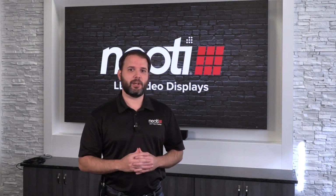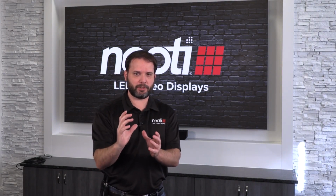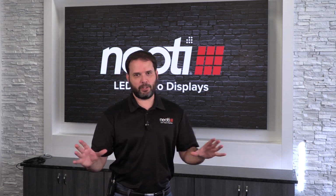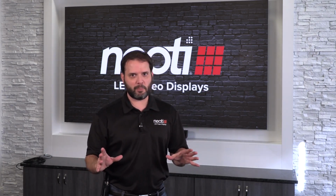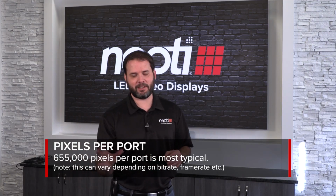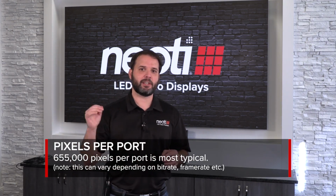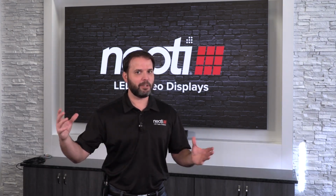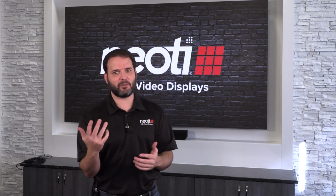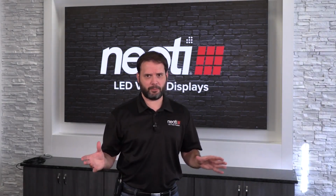Current DirectView LED systems have a load capacity limit of pixels per port. So how many pixels can that port drive? The easy answer that's most common and most typical for everybody is the magic number of 655,000 pixels per port. There are some variables that can make that capacity number go up or go down, and we're going to look at what causes those variables, and the math behind how they get calculated. So let's look at where 655,000 even comes from.